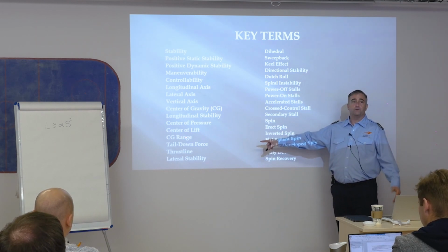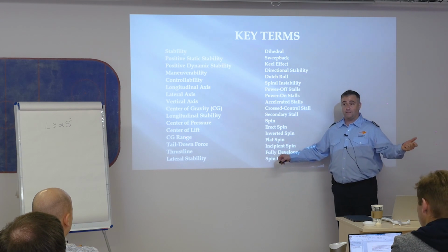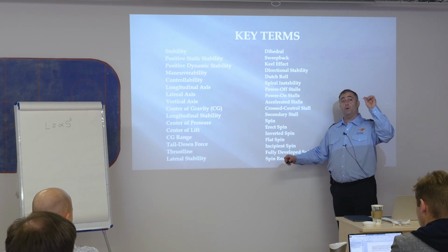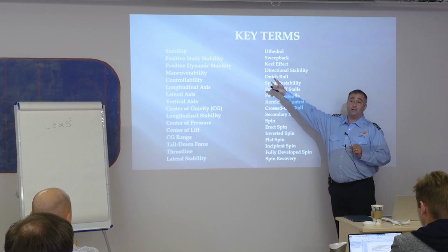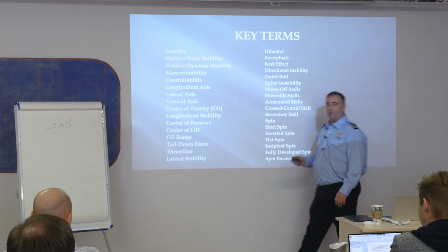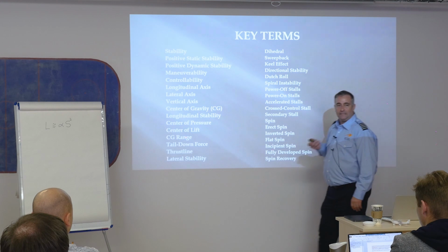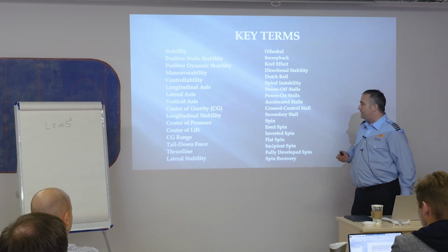Tail down force, which helps describe my stability. This is how engineers built these airplanes in such a manner that they will be predictable and exhibit positive static and dynamic stability. Thrust line, if I add thrust or take away thrust, how does that cause a pitching moment in the airplane?